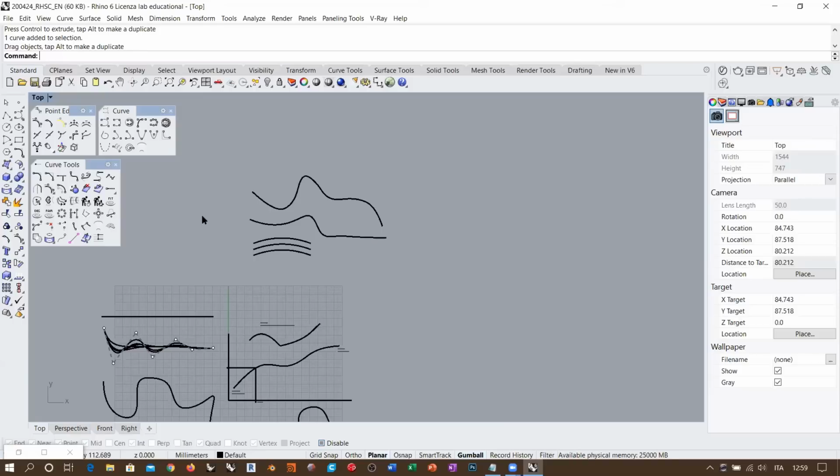This is the general meaning, but fairing in terms of topological control means avoiding the G3 discontinuities or G3 variation. So avoid the jerk phenomenon, like the curve starting to dance around and oscillate around. So fairing tends to eliminate this kind of oscillation and make a curve easier to manufacture, more aerodynamic, more smooth, and so on, okay?